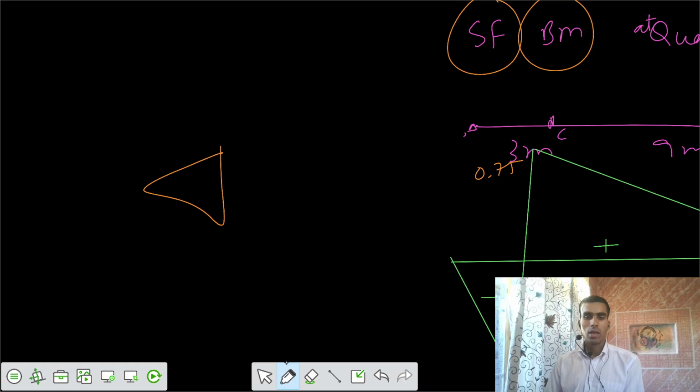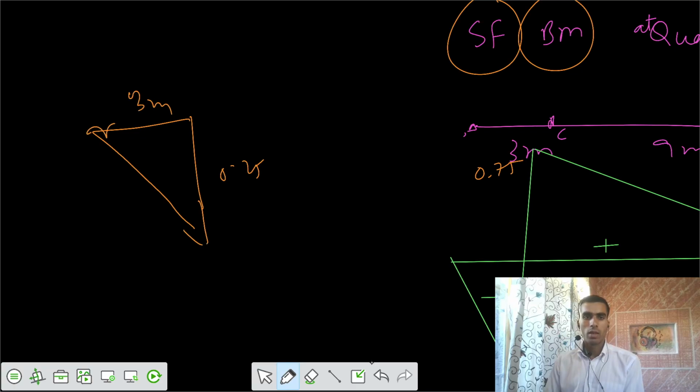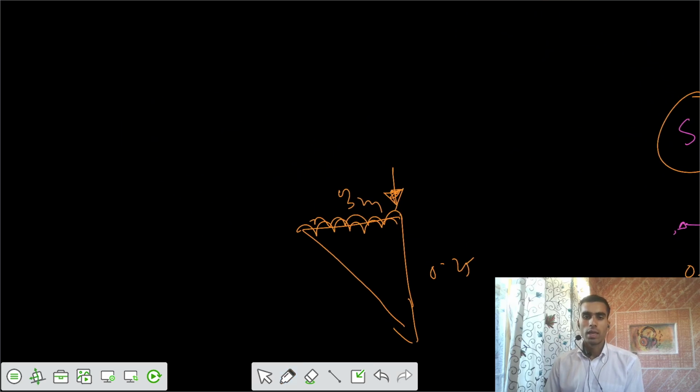if you want to write for the negative, we have the ordinate of 0.25 and length was 3 meter, and you can keep the UDL for this part only, and you apply the point load at the peak ordinate. So you can get the values, that is, what is the V negative maximum.